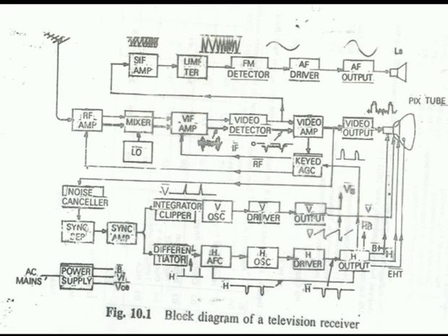and the color burst signal. Here the video preamplifier amplifies the signal strength from 2 volt to 6 volt so that it is able to drive the video output stages. In this stage, the division of chrominance and luminance takes place. From the video preamplifier, the video signal is coupled to the chroma bandpass amplifiers through the chroma filter circuit and the synchronization separation and delay time circuit.